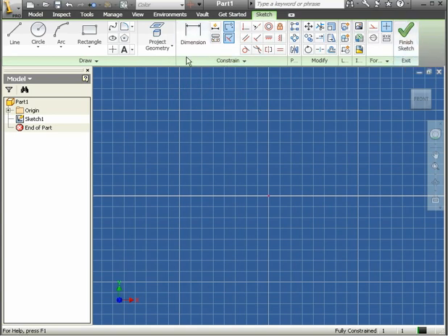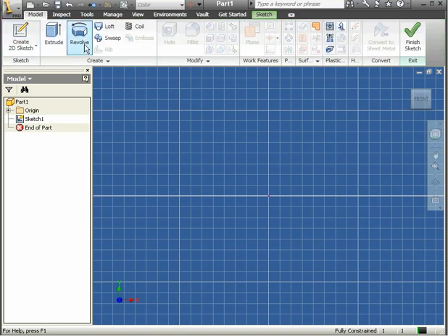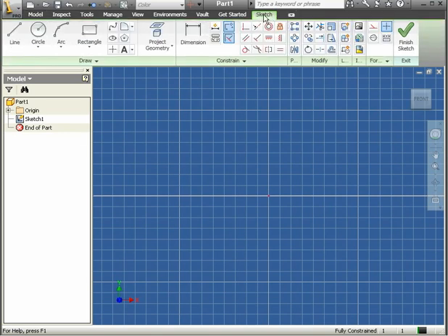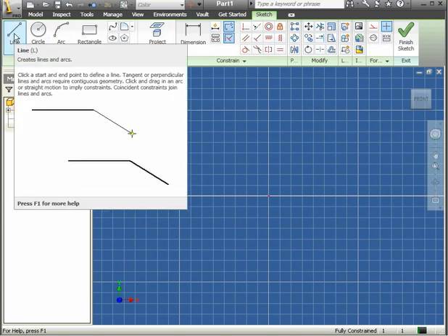While I'm in the Sketch environment, if I click, for example, the Model tab, we can still see that the Sketch tab is active by its highlighted color. Do you remember the panel bar in previous versions of Inventor? Well, the ribbon basically replaces this. There's a number of convenient help tools that are easily available. When you mouse over a tool, a short help pop-up window appears. If I hover longer, an extended help pop-out appears with a description of how to use the tool and an example. I can also press F1 on the keyboard to read more about the tool.